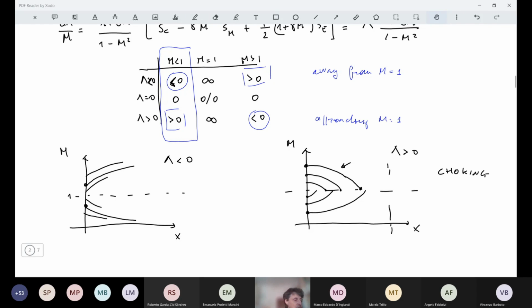So you can imagine this, and we will discuss it later for the nozzle, but you can imagine that we cannot fill the channel with any mass flow rate. If you try to put inside more than allowable, you will have something that is not possible. So there will be some mass flow rate that will not be able to enter your channel. So there will be a shock if you are considering supersonic flow, and there will be some, let's say, bleed of the flow outside of the channel if you are considering subsonic conditions, and the inlet Mach number will adjust, for instance, to this value here or to this value here to get Mach number 1 at the exit.